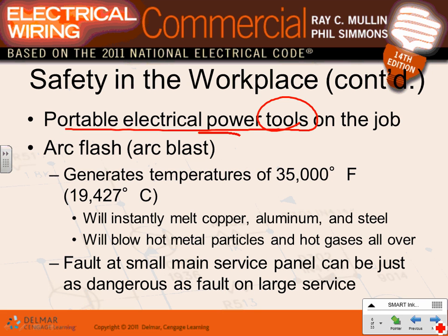Arc flash, arc blast. This is the most dangerous, as I said, guys. We go through it in more detail. If anybody wants more, I have 4 hours of OSHA and 70E training on YouTube. If anybody wants to go there, you get detailed stuff about arc flash. Long story short, you open this panel, Jeff, you drop a screwdriver right in, a big ball of fire comes at you, and that big ball of fire, typically, unless you do the calculation for it, is 5 feet. So the boundary of that ball of fire is 5 feet.